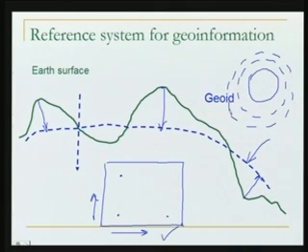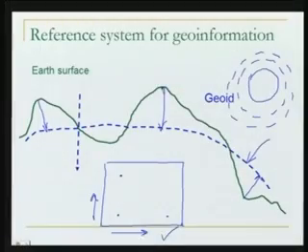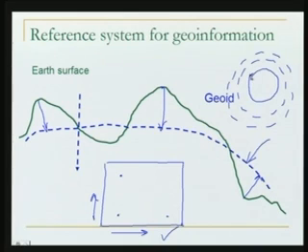Not only one, we can have many geoids, because each of these surfaces will be equipotential, as in this case. So it's like an onion, you can peel it off, there are many layers. Similarly, there will be many level surfaces which are possible, all equipotential, all satisfying the condition of being the geoid. Well, as we were saying, we can project our points onto the geoid, but is the geoid mathematically definable? To look into that, if you look inside the earth, the distribution of mass is not uniform.